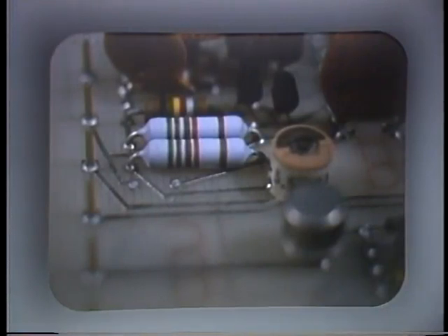Even passive components, such as these axial-leaded resistors, can be damaged by static zap. If we look inside to see what has happened, we see this area of metal film, which has been grooved in a spiral so as to make a long resistance element. Right here is the site of some static damage. Let's increase the magnification and see what it looks like.